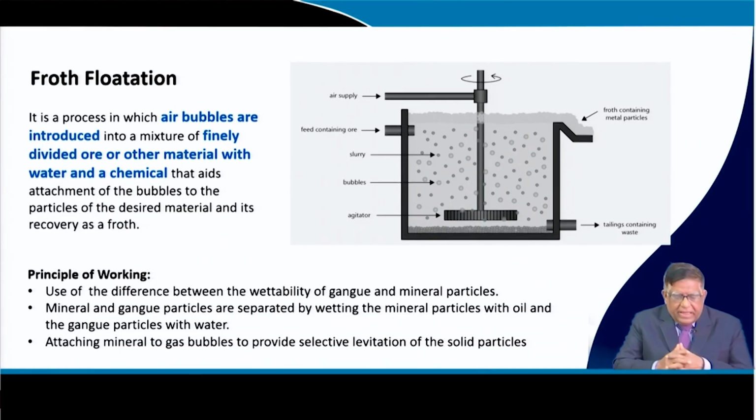Depending on how they get attracted to that oil, they get picked up by these bubbles. As you know, because of buoyancy, bubbles have more free volume inside, so they come up to the top. In that environment of agitation and air, these bubbles make the foam or the froth, and that froth you take out.